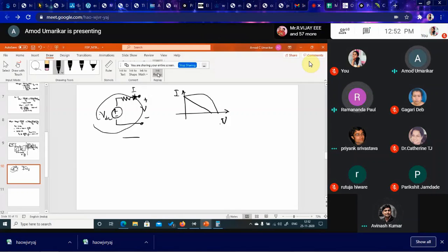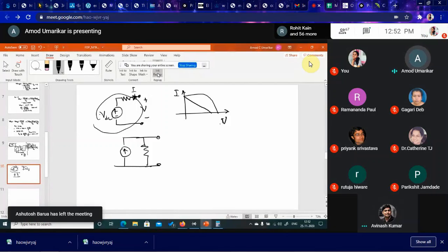Our motive is to get the maximum power. Maximum voltage is V_OC. We need minimum series resistance and maximum shunt resistance, which can be helpful to improve. When we see big solar PV systems, they are operating on MPP.